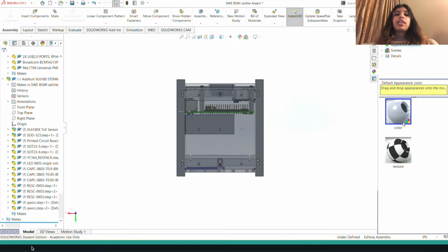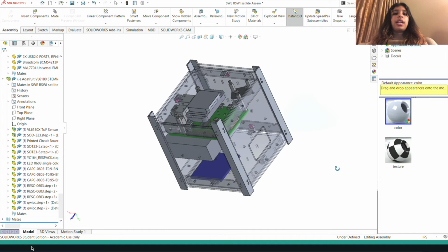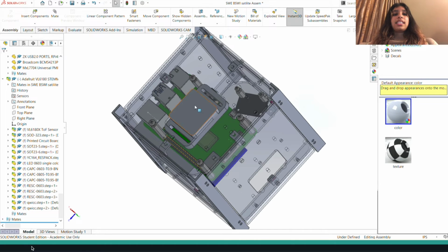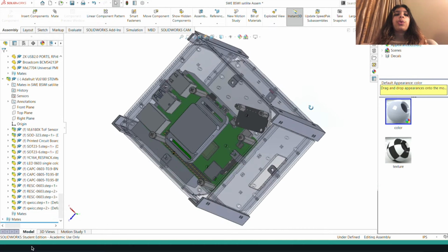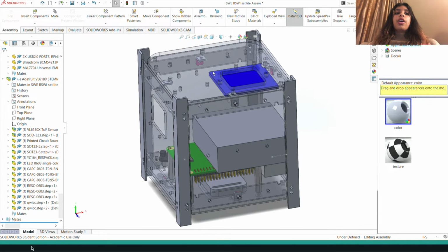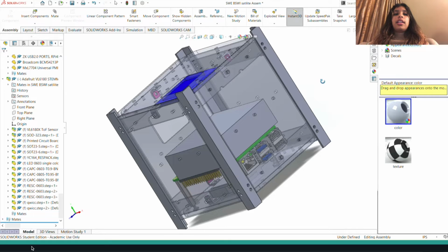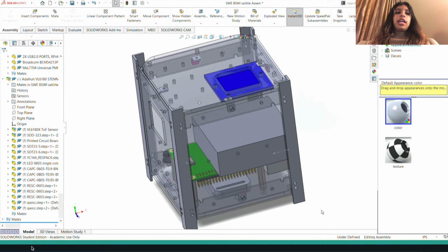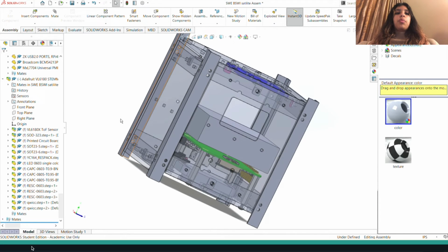Here is our current CAD model for the satellite. Let's start at the base, where we use the FlatSat as inspiration on how to attach the camera, IMU, and Raspberry Pi to the satellite. For the structure, we realized the holes were wrong in the angle brackets, so in the CAD, we created double holes to make sure it aligns. We then used the instructions to create the structure using the newly drilled angle brackets and the polycarbonate pre-cut panels.